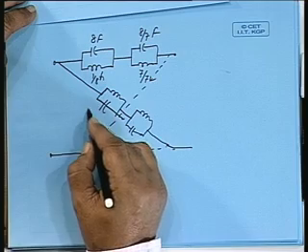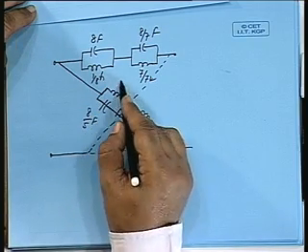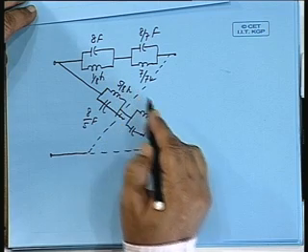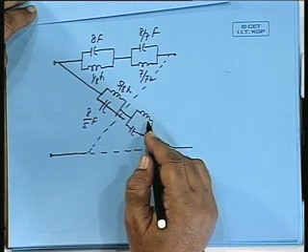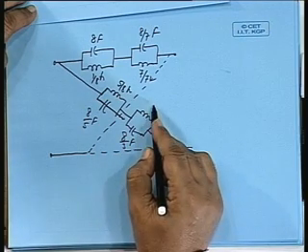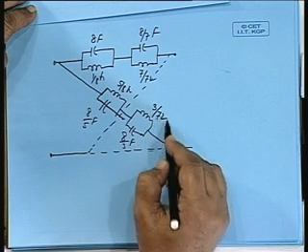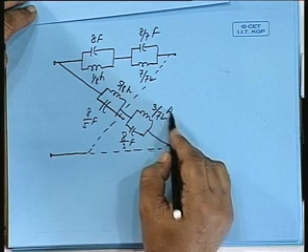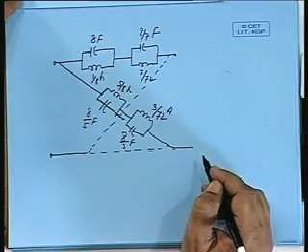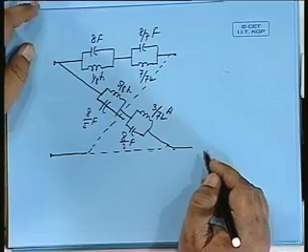So, 8 by 5 farads, and 5 by 8 Henry. Similarly, this one 3s by 8s squared. So, 8 by 3 farads and 3 by 72 Henry. So, these are the element values. There are a large number of elements coming, but the network is very easy to realize.